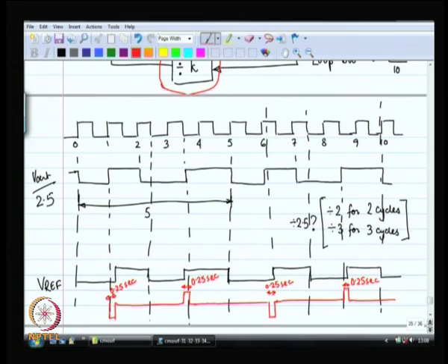Now, this looks brilliant, does it not? Up and down of equal durations, different points of time, of course. This is beautiful, is it not? It is very nice, which means if everything is perfect, nothing is going to change as far as the control voltage is concerned. If nothing changes as far as the control voltage is concerned, then the output of the VCO does not change, which means you have got lock. So, you have successfully divided by 2.5.